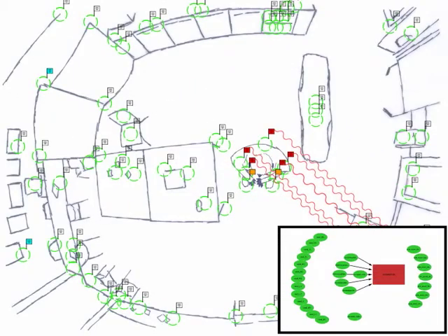If the framework detects such a sensor, like the shoe sensors of the person, indicated with the orange flags and the recoloring of the sensor bubble to orange in the framework sketch, this learning candidate is connected to the sensing ensemble in a way that it is being trained with the labels generated from the ensemble of the sensors attached to the jacket. The labels sit, walk and stand are transferred to the shoe sensors, and the quality of the learning process is checked according to the comparison of the output of the teacher and the learner that is done periodically after a certain amount of time.